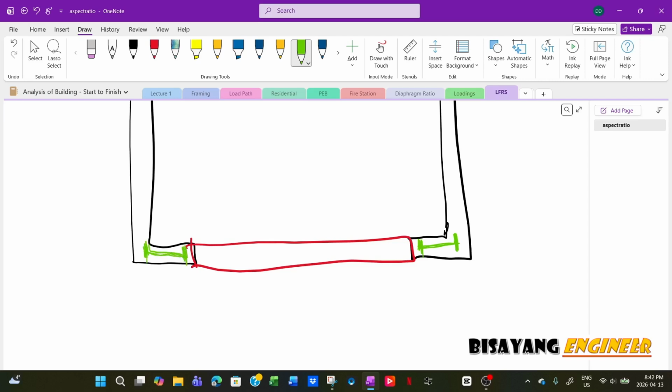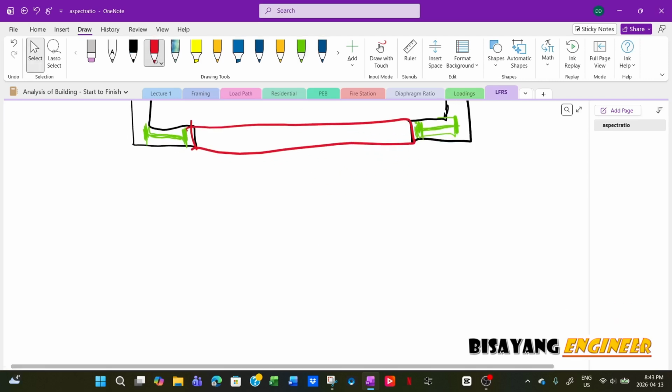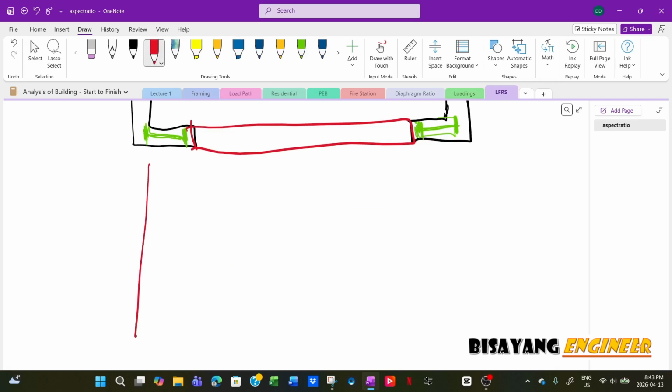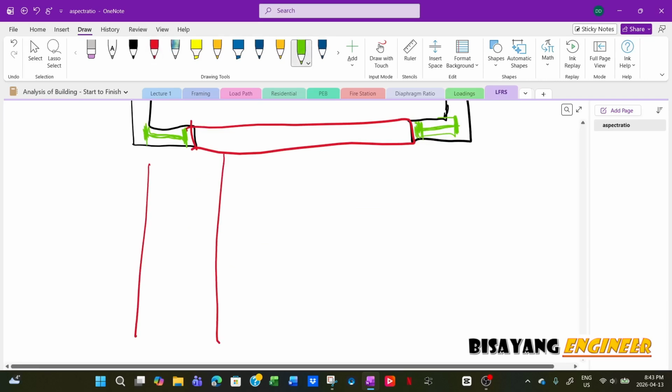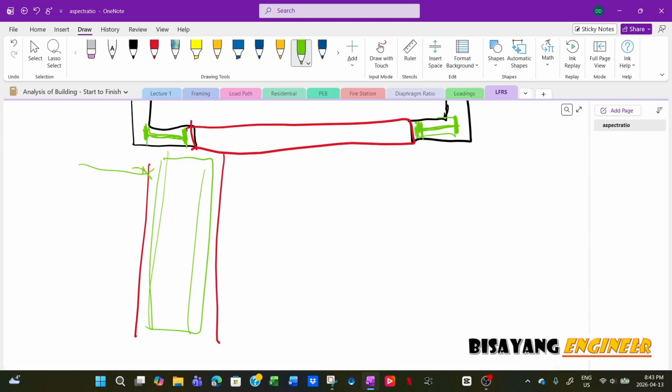And all it does is just to resist. This is a cantilever. This is a movement at the base because this is a cantilevered column. So if you look at the elevation, this is the wall, right? And then this is right here. It's just a cantilevered column, and it will resist the reaction from the roof diaphragm. This is basically a cantilevered column with concentrated load.